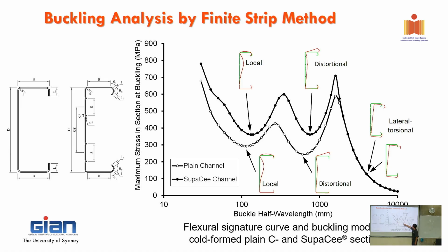And the distortional buckling, you can see the lip going up, and because of that folded lip, that actually pushes that one here. See how much that is pushing up. So when you run this by introducing only a little bit of that to the section, it increases the buckling capacity about 15%. Okay, we're not talking about strength now. We're just talking about buckling capacity. It's going up about 15%.